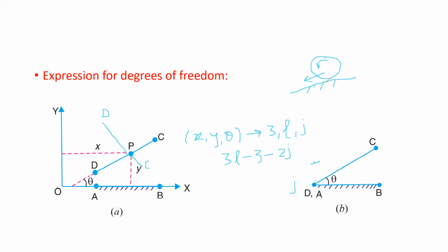The point of contact will not change, but the coin will slip ahead without rotating. That is called slipping. So here turning is happening and slipping is also happening. So we say that the joint formed between the coin and the surface is a joint with 2 degrees of freedom.